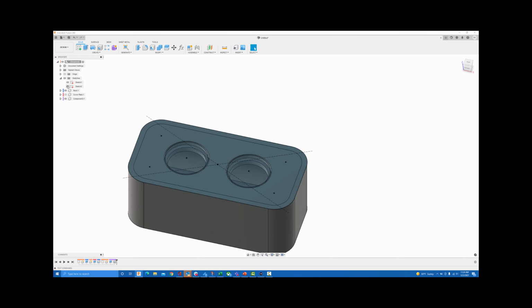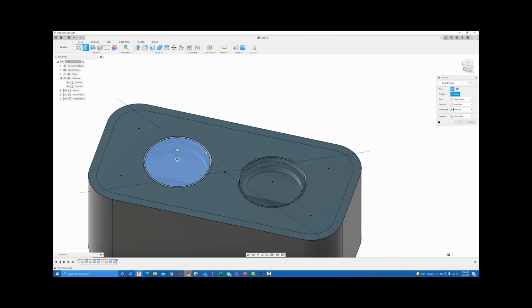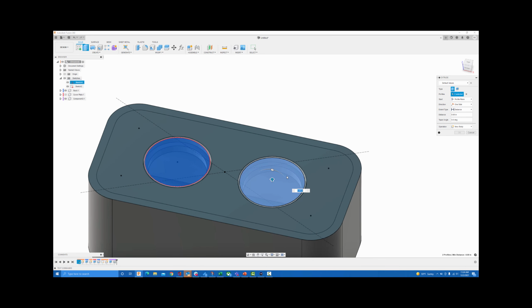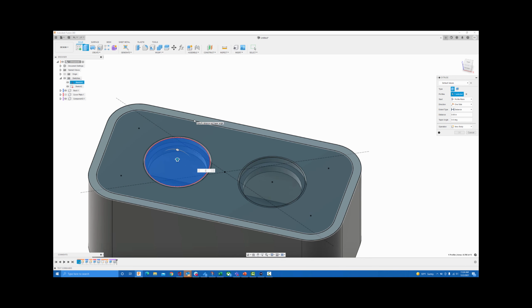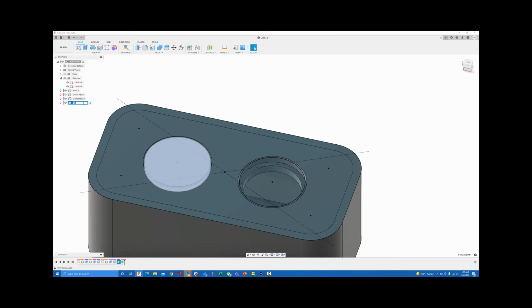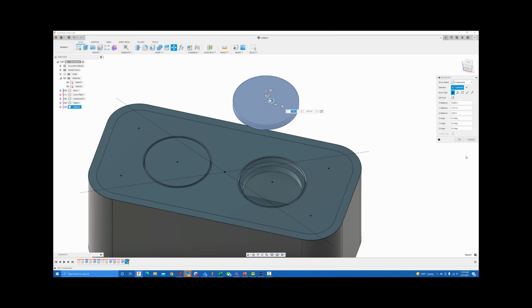I know I'm kind of going through this fairly quickly, but let's grab that piece, and in fact, we'll just do one of these and make one piece of glass. Let's just clear out my selection. We'll grab that, say minus 0.1, new component, and that's going to be a piece of glass. And then with that, I'm going to do a copy, and we'll do a paste, and you'll see that it'll give me another glass piece with an occurrence of 2.